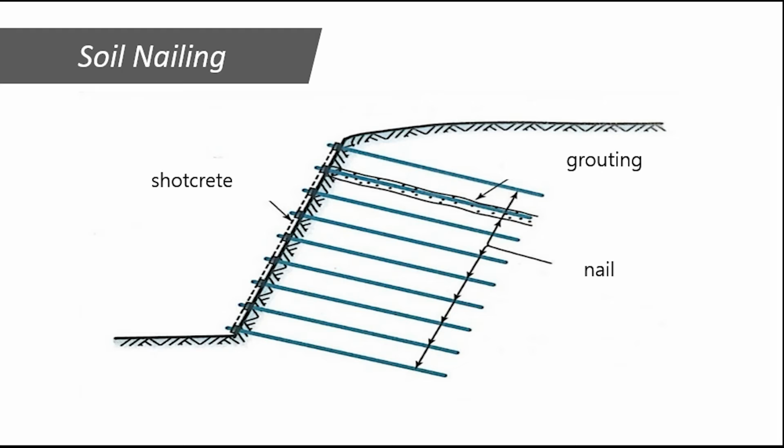The advantage is that it has excellent water quality, cheap construction cost, retaining walls can be built, and rapid slope construction is possible. The disadvantages are that it is difficult to predict the effect of freezing, difficult to construct wall drainage, and the horizontal displacement is larger than the pre-stressed anchor, so construction management and quality control are relatively difficult.